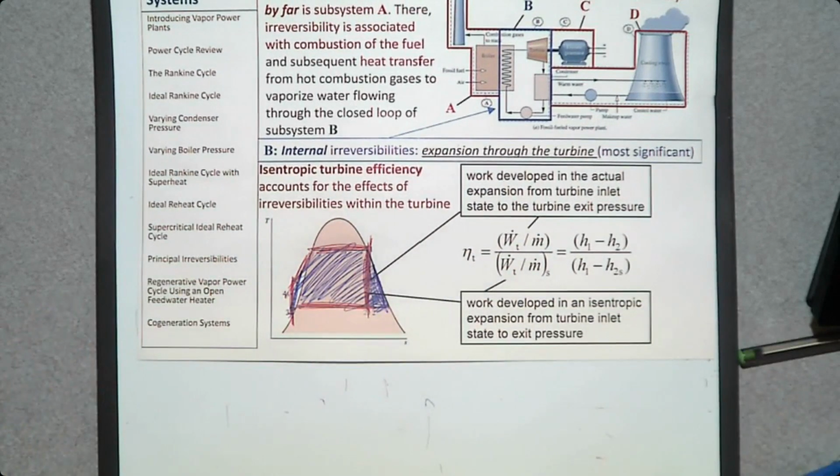Then you may have a question. I think the blue looks bigger than red. So something is wrong here, right? So our understanding is that when we have an ideal Rankine cycle, we should have the largest enclosed area. But due to the irreversibilities, there is an entropy increase. So there's a slight decrease in the area, but there's a much larger increase in the turbine. So the actual enclosed area, blue, should be larger than red. Am I right or wrong?